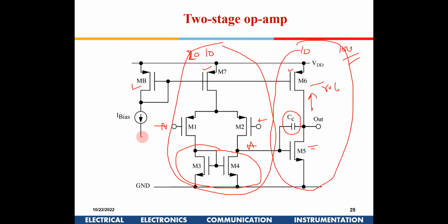Yeah, that one. Why is it floating? This is floating, you are saying? Yeah, why is it floating? When you show a current source, it means this current source is being generated by some circuitry which will pull I bias here, which will be relatively independent of VDD and temperature variations. These are known as band gap circuits.